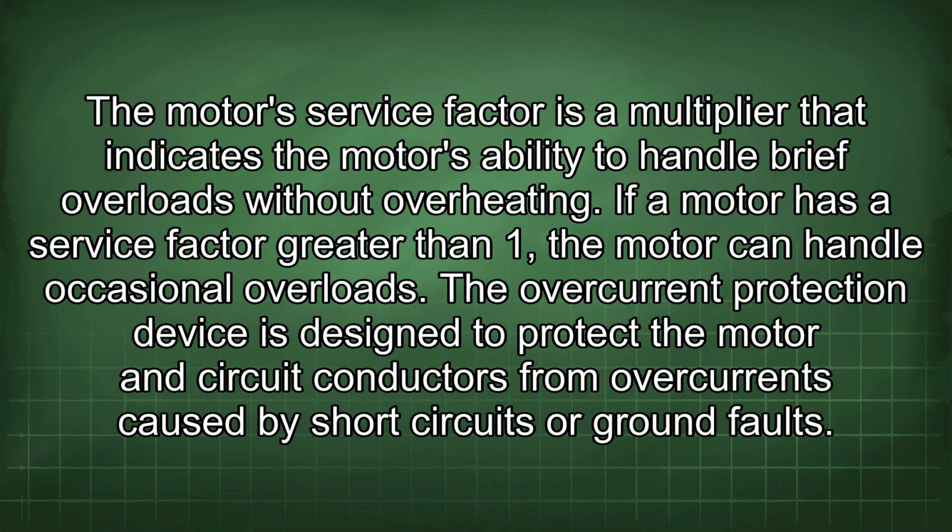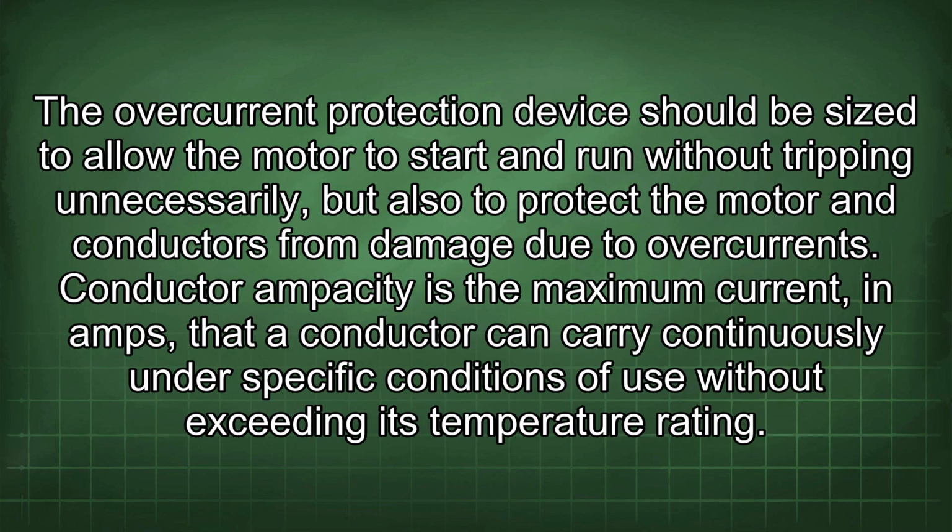The overcurrent protection device is designed to protect the motor and circuit conductors from overcurrents caused by short circuits or ground faults. The overcurrent protection device should be sized to allow the motor to start and run without tripping unnecessarily, but also to protect the motor and conductors from damage due to overcurrents.